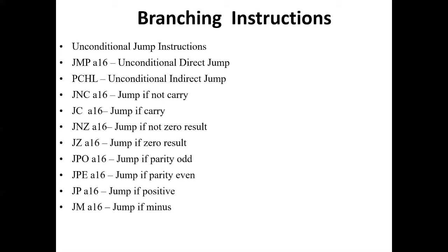Next is JPE A16. JPE is a mnemonic which stands for jump if parity even. This instruction is used to jump to the address A16 provided in the instruction only if parity flag value is 1. If parity flag value is 0, program flow continues sequentially.